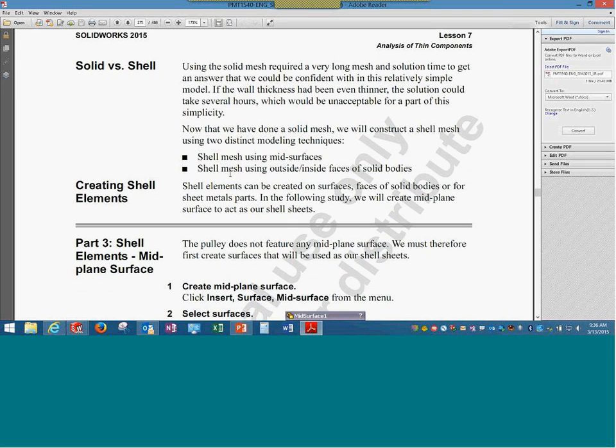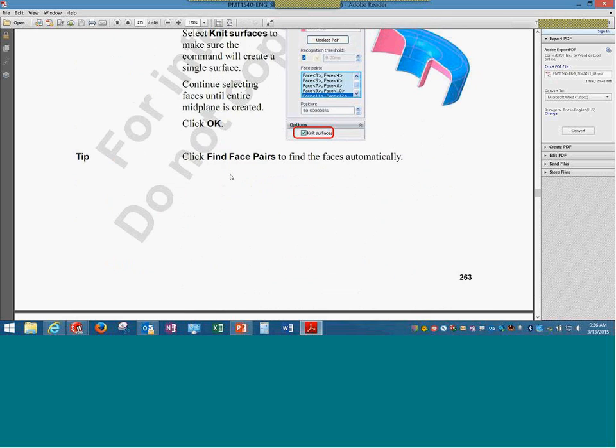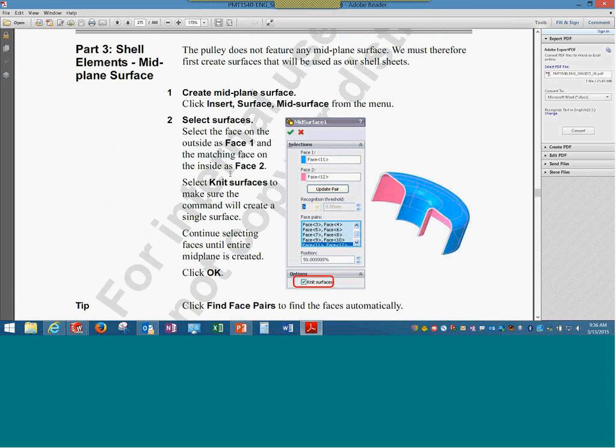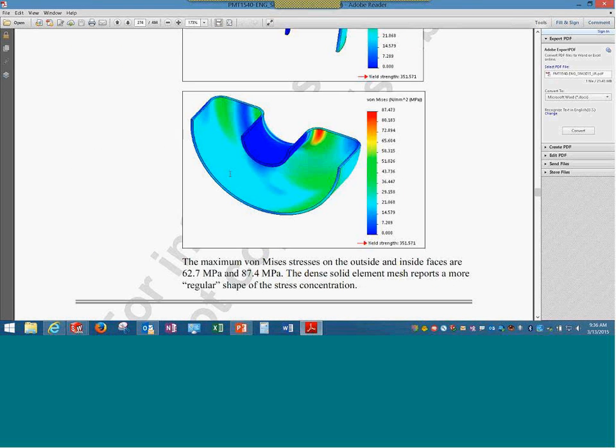Shell, yes. So as discussed in the last few sessions, do this comparison of solid versus shell, etc. But please remember, when we are moving from solid to shell, it is with a reason, and the reason is I cannot mesh the solid geometry with solid elements, and I want to use shell elements. Obviously, we are moving because we are not able to get accurate results using solid elements. So there is a point in comparison.